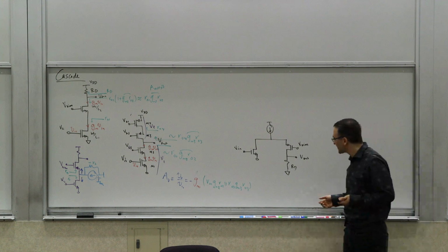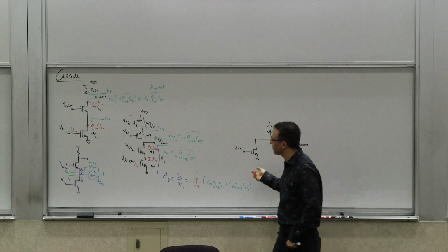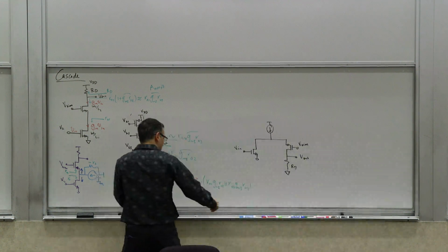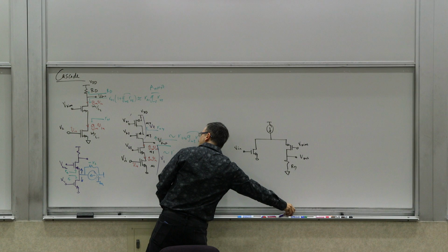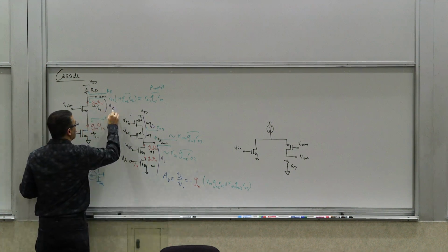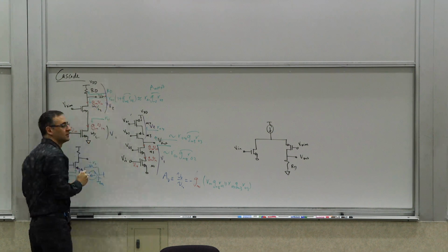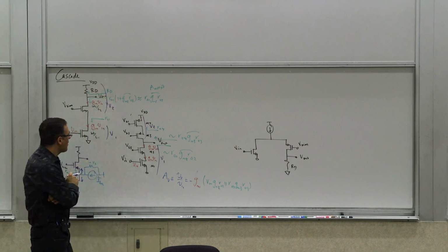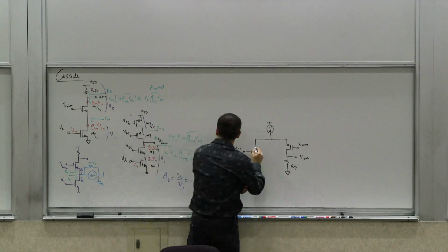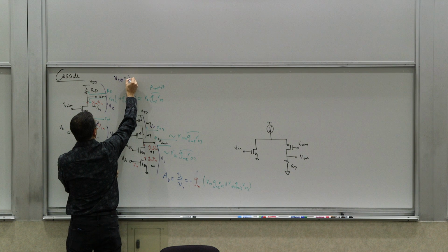The idea of folded cascode is, let's see what the voltages look like. We could even make it a double folded cascode. So let's say we were talking about singles for a second: the DC voltage across here was V1, and here we had V2, or the entire thing, let's say, is V2. The total VDD was basically V1 plus V2.